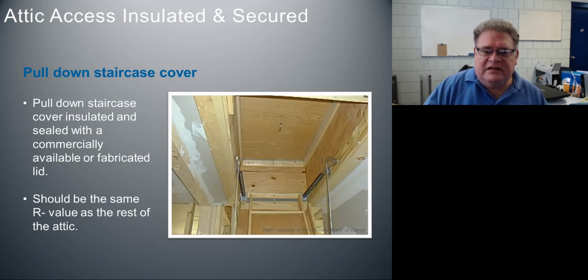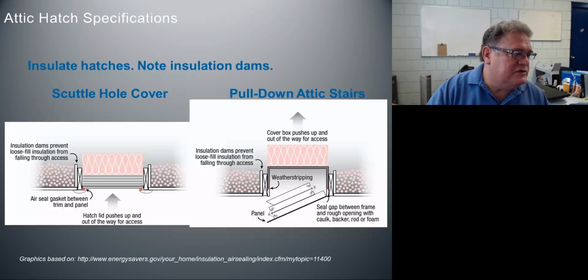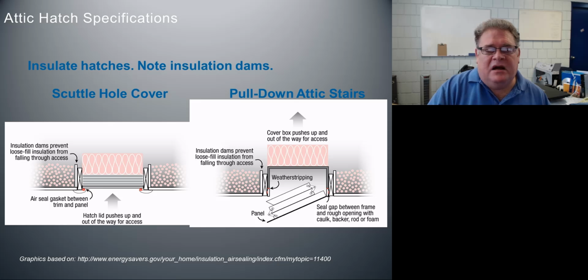It should be the same R value as the rest of the attic. Our standards call for any attic access or scuttle hole to be insulated to the surrounding structures, which in this case would be the attic. So if we have R38 in the attic, we need an R38 attic hatch. Alrighty.